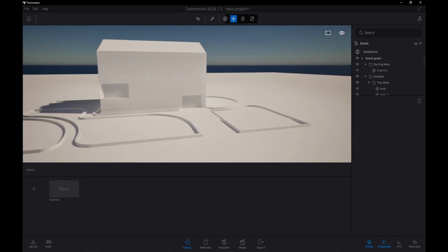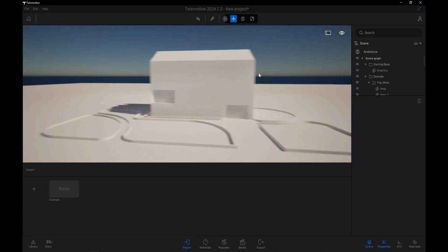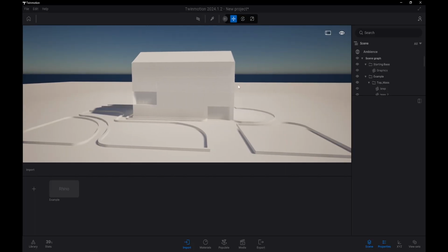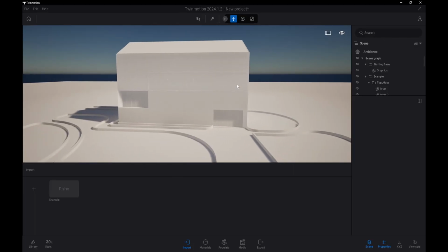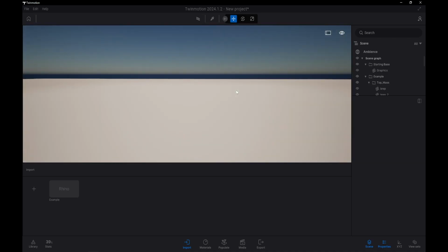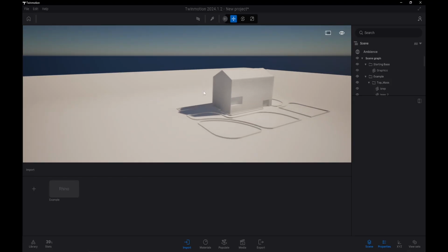And then your mouse navigation: right click, you see how I'm orbiting. And then with the mouse wheel, I'm panning. Scrolling the mouse wheel, I'm zooming. And again, if I press numbers, the zoom rate is going to change, you know? So that's basic navigation.